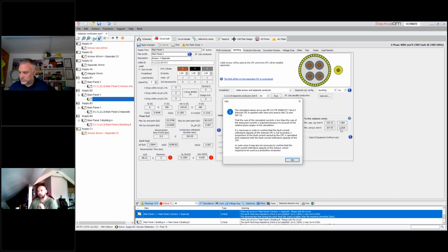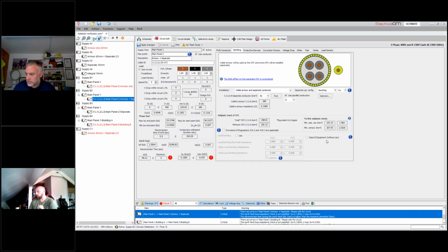These numbers may not add directly up to the specific value here, and can be higher than what you see there, because these are based upon the tested values, and it's mainly to do with phase angle and those sorts of things. In the calculations provided in the document, they haven't recorded the difference in the phase angles for power factors and those sorts of things. So I just want to show that as information in there as well.